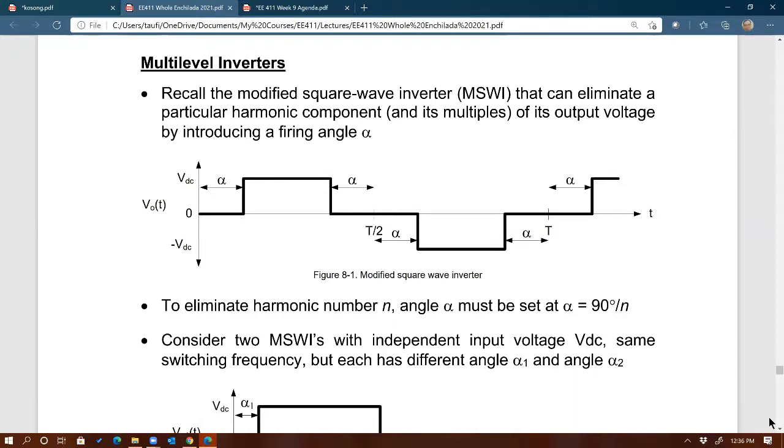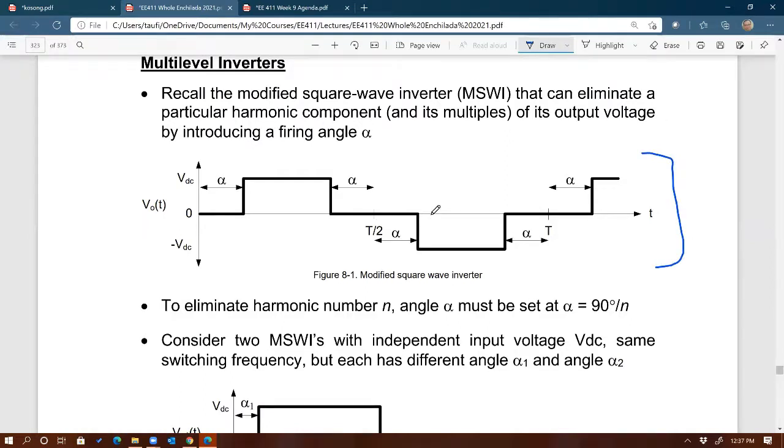So having a flat AC like this would be okay, because imagine if you rectify this, then you get a more flat DC, except that you're going to have gaps, which you can filter. So for some applications, having this shape is fine, especially if you rectify and then filter it. So that should be okay.